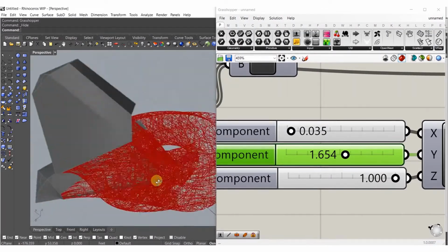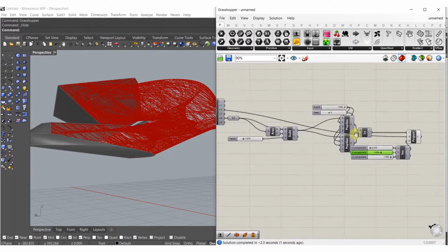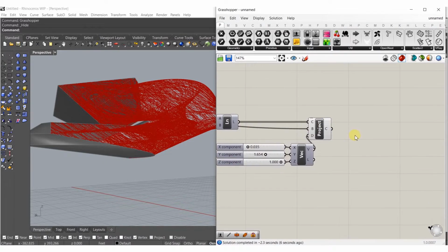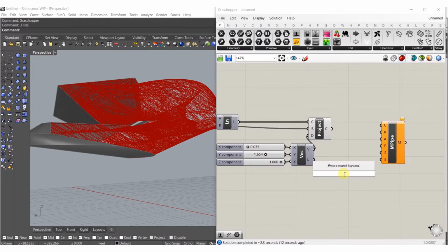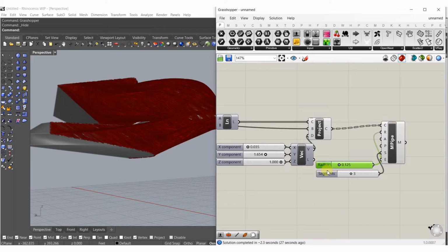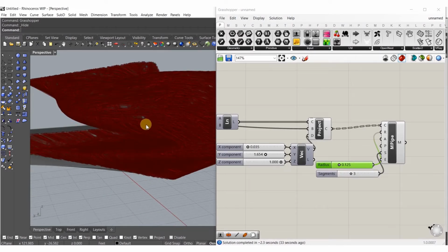Okay, and then those lines, all I'm going to do is make them mesh pipes. And I'm going to use mesh just because it'll create less geometry and it'll run quite a bit faster. And we'll make the radius pretty small for now. And the reason why I put segments in first as 3 is just because it'll run exponentially faster rather than having the default, which I think is 10. It's just more geometry, so 3 is by far less geometry on the mesh. It looks like we need to change the radius just so we can see through it just a little bit.